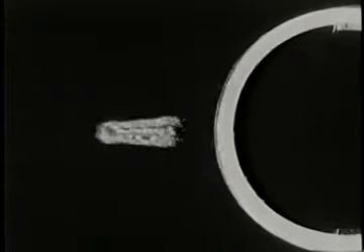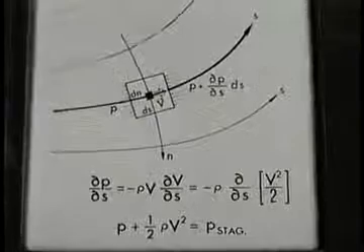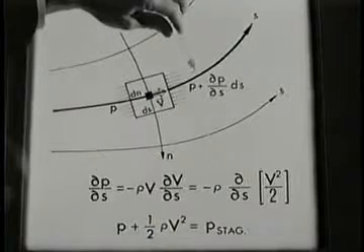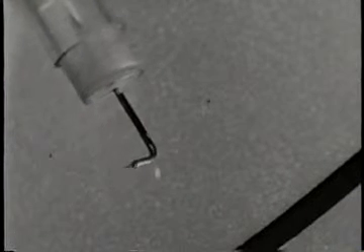On both sides of the unique stagnation streamline, the fluid decelerates, but not to zero speed, and then slides around the sides. The stagnation point is put to practical use in a pitot tube. The hole at the nose measures the stagnation pressure of the particular streamline reaching the hole.